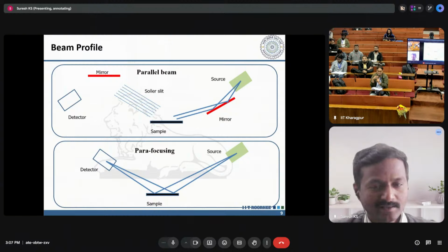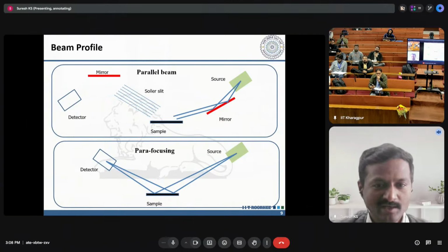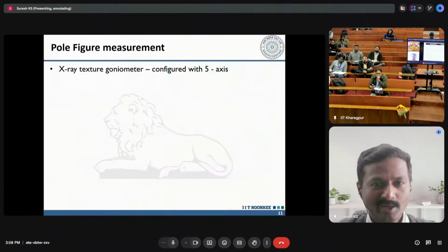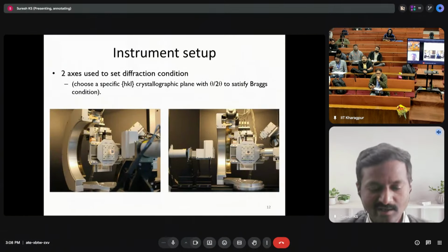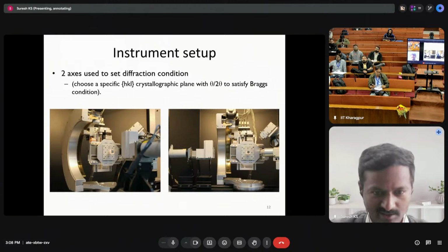But now if you have a much larger grain size, for instance, if your grain size itself is several hundreds of microns, then in that particular case, the 1 centimeter by 1 centimeter sample alone may not be sufficient, but rather you may have to go for something like 3 or 4 centimeters. But then the opening in front of the X-ray, in none of the detectors do you have more than 1 centimeter, or in extreme cases you can have about 2 centimeters also.